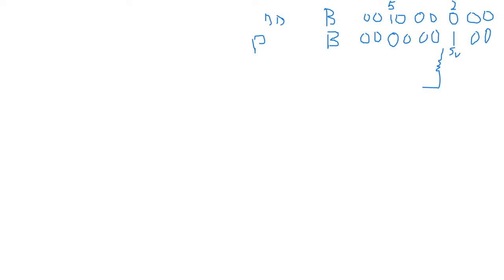So now what we want to do is to read the state of a switch. We've got our ATmega32A, and then we have 2 pins we are interested in, all on port D. Now we know that PIN returns the status of that particular pin we are interested in.